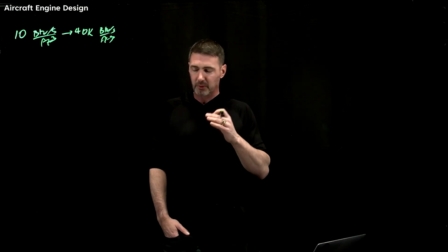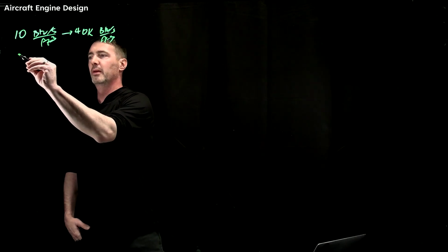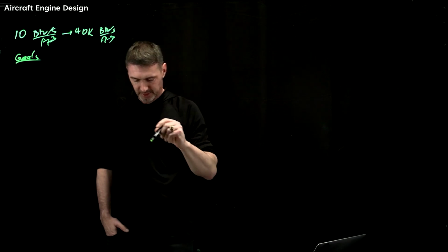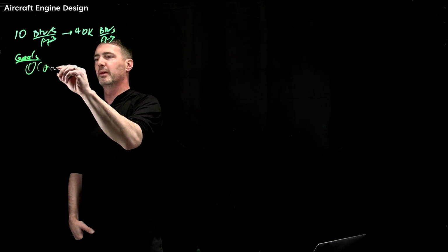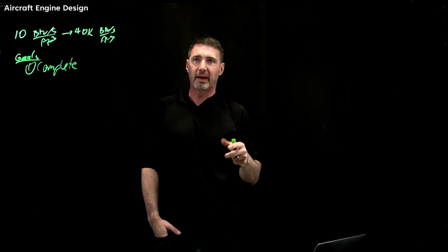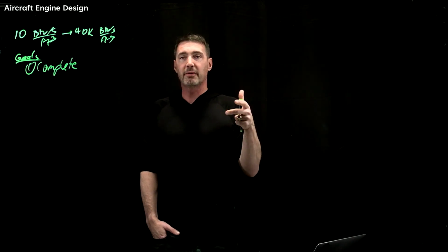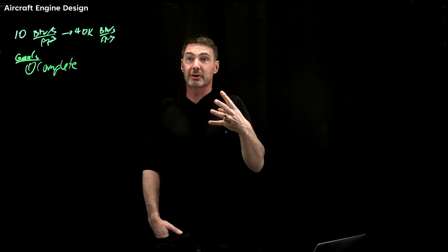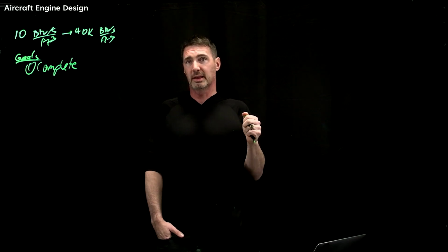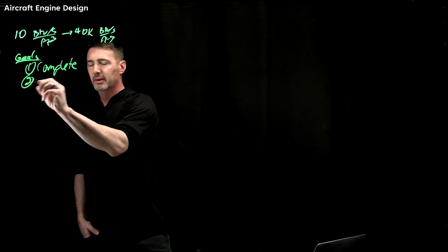And so when you talk about the burner and the different things you want out of a combustion system, the goals of combustion, let's list them out. The first is you do want complete combustion. You don't want any hanging hydrocarbons or things like that. We'll talk about emissions in a second, but just from a pure standpoint, I mixed the fuel with air, our oxidizer, and had combustion. You really want the full complete process in that combustion. So that'll drive a lot of design.